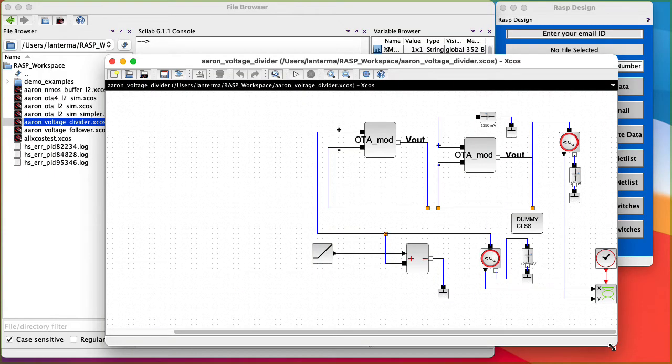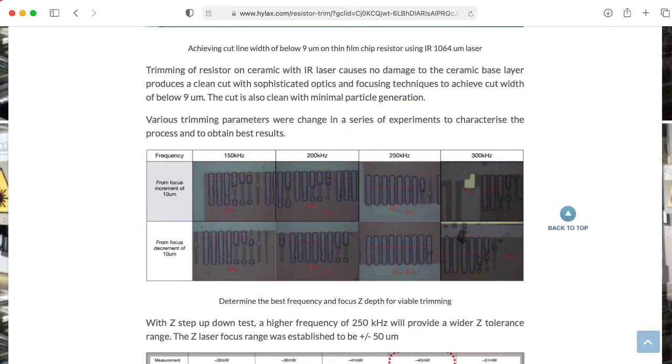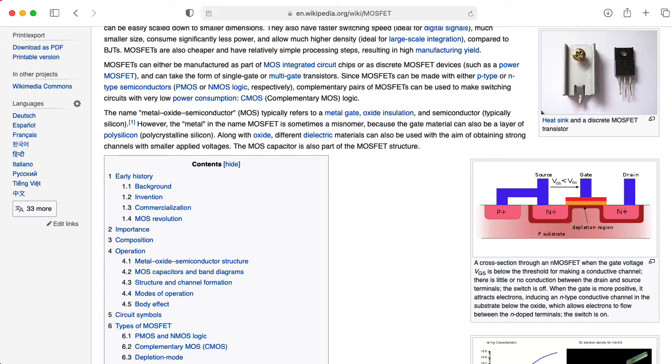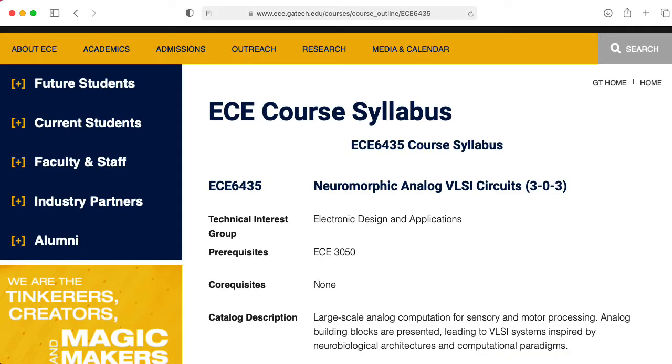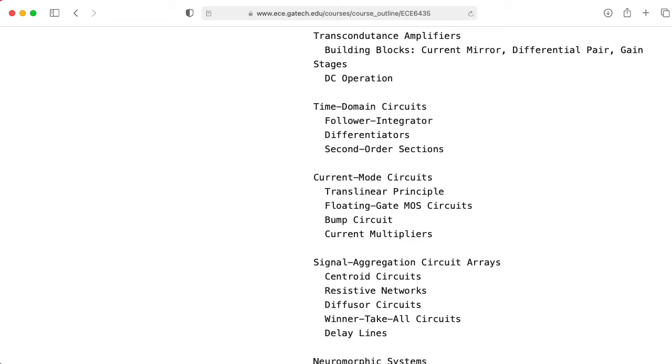But on a chip, like this field programmable analog array that we're looking at, resistors are actually fairly bulky, complicated things, whereas transistors are essentially free. So you'll see people trying to avoid using resistors and using transistors instead. And that takes a while to get used to.